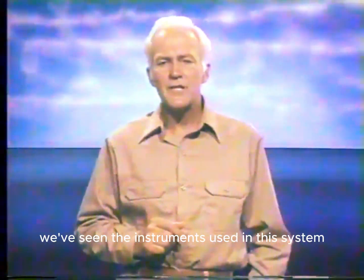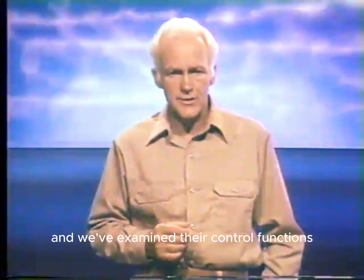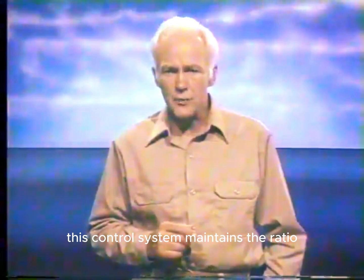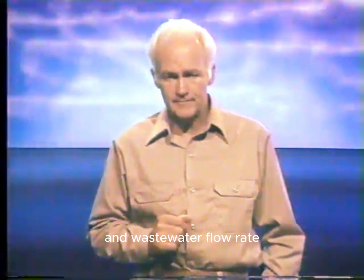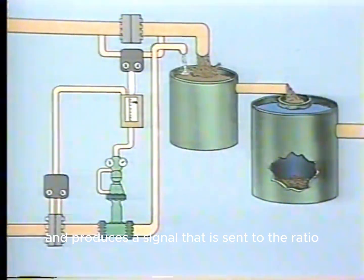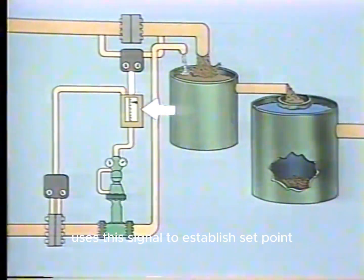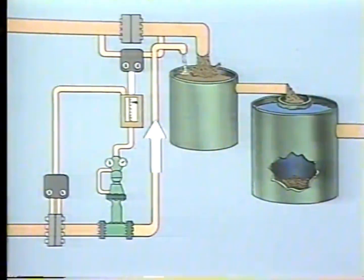Up to this point, we've seen the instruments used in this system, and we've examined their control functions. Now let's see how this control system maintains the ratio between chemical solution flow rate and wastewater flow rate. This flow transmitter measures the flow rate of the wastewater and produces a signal that is sent to the ratio controller. The ratio controller uses this signal to establish set point for the chemical solution flow rate.